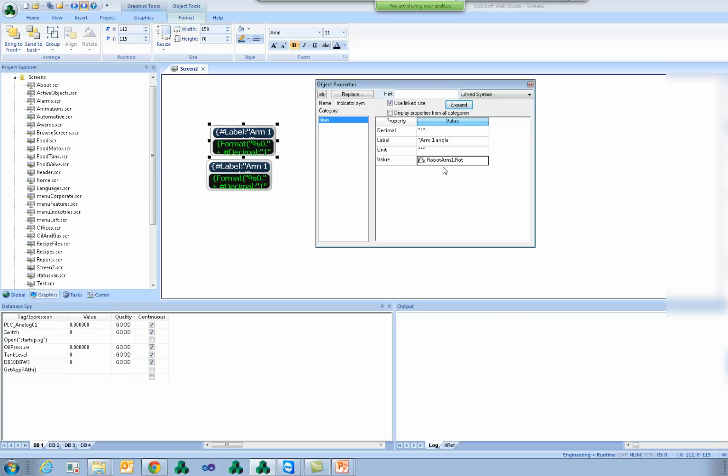For example, you have a symbol where you're going to enter the door number or the door name or something like that. It may be good that you allow the user to type something and then you get that information, and only after that you display that information. But you want to do that inside a symbol. So that's a case, for instance, where you could be using indirect tags as a property value inside the linked symbol. Okay, if I properly understood what you mean with indirect tags and not exactly the property name on it. Okay.